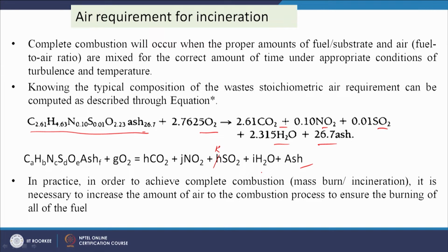In practice, in order to achieve complete combustion, that is called mass burn or incineration, it is necessary to increase the amount of air to the combustion process to ensure the burning of all the fuel. These reactions require some oxygen stoichiometrically, but if we provide only this oxygen, we will not get complete combustion. Always some excess oxygen or air has to be provided.